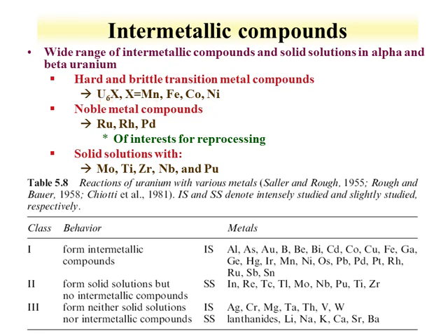So that intermetallic has specific stoichiometries, and these compounds will form. So if you had uranium metal against stainless steel, which can occur in a fast reactor, and you started to have diffusion of the stainless steel into the uranium, you would change that uranium metal to this intermetallic compound. Noble metals can also form compounds with these intermetallic compounds with uranium.